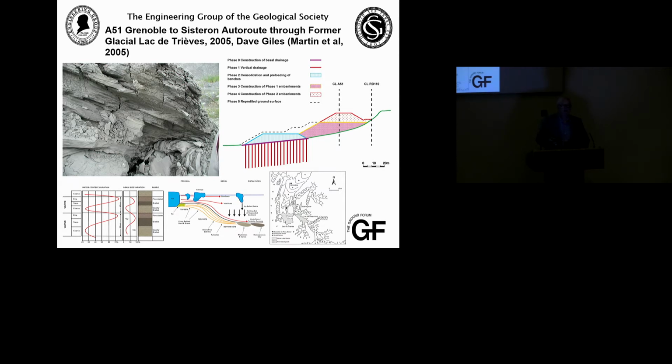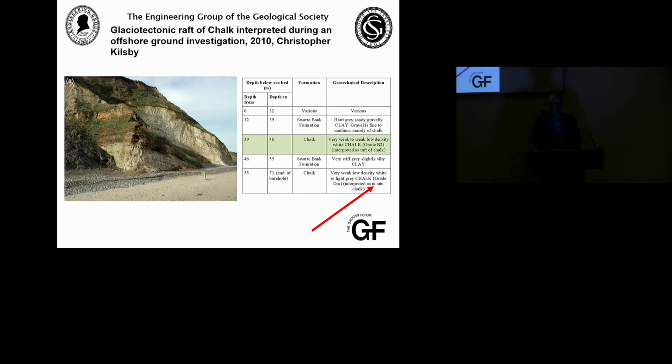The material was very prone to liquefaction failure. If it was disturbed, you would completely lose the strength of this material. There are very large landslides occurring there. So the fundamental paleogeography linked through to the depositional environment, linked through to the geotechnical variability was part of that developed ground model. So integrating all of those different disciplines, feeding through into the construction project.